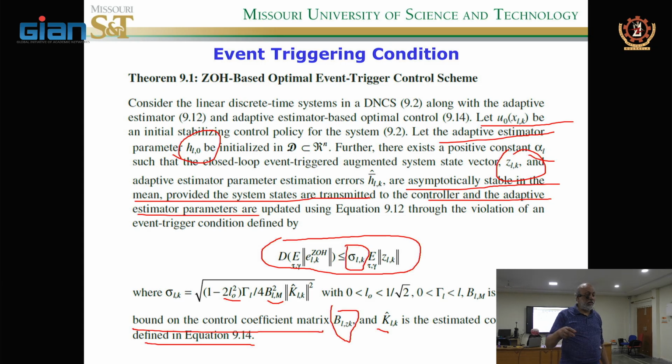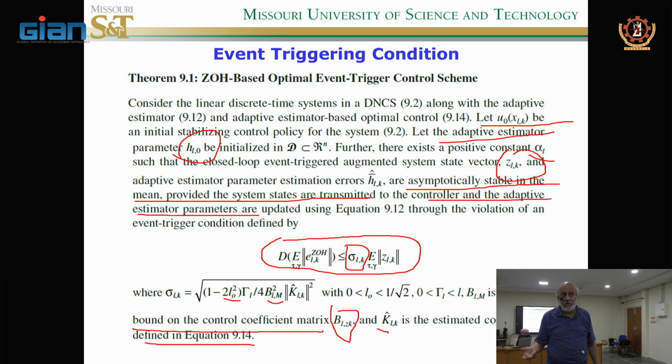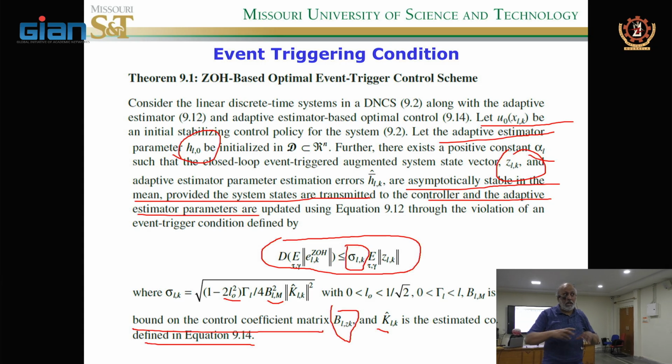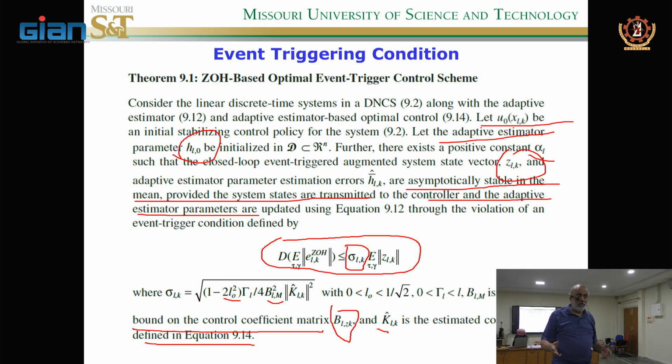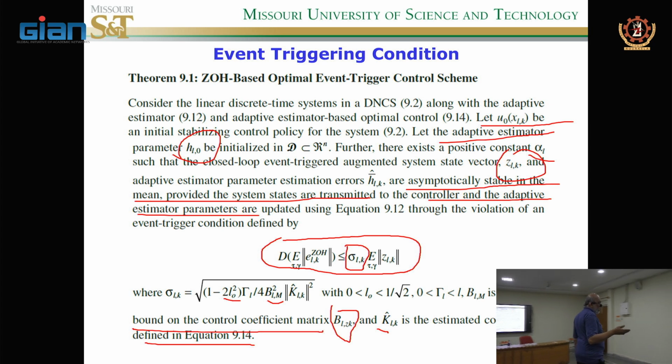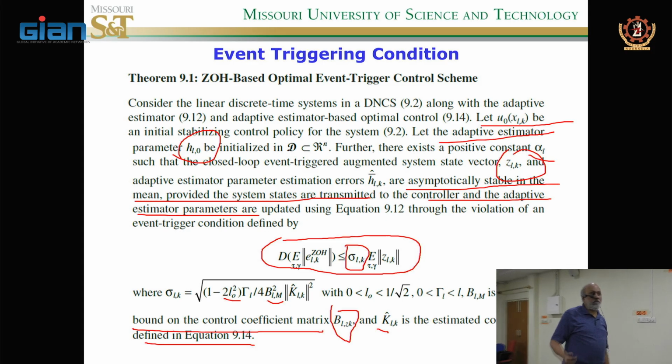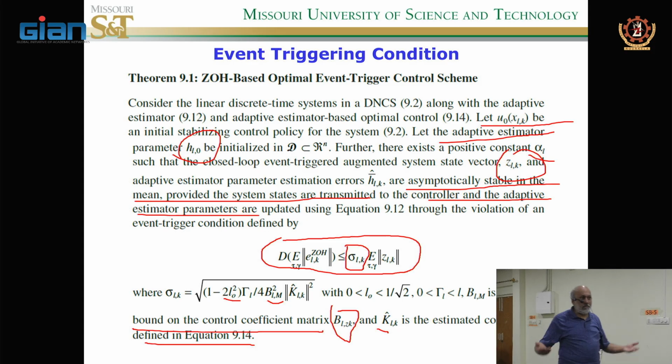So now they used what they call collision avoidance. This way at least the subsystem that is transmitting continues to transmit, and the other one can listen and then back off. So CSMA/CA, carrier sense multiple access with collision avoidance. You want to avoid collisions rather than collide.